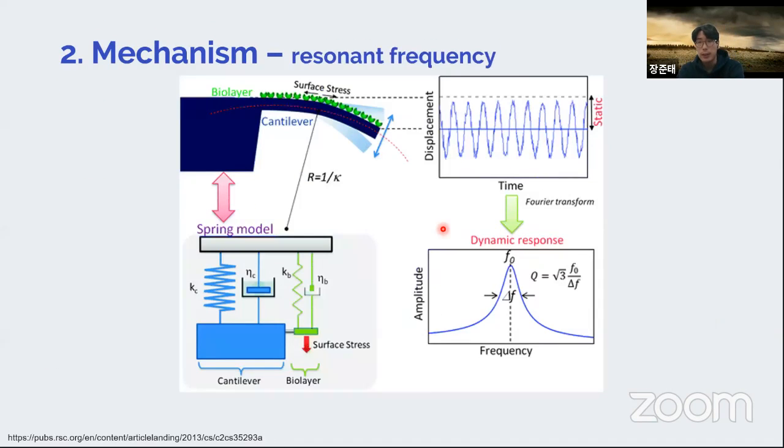And last is the resonant frequency method. As I mentioned before, in dynamic mode, they use resonant frequency. In this picture, they use some resistive method, but we can use all kinds of methods I've presented before, like optical, piezoresistive, capacitance, MOSFET method. The pro of dynamic mode is definitely accuracy because they use vacuum as the medium.